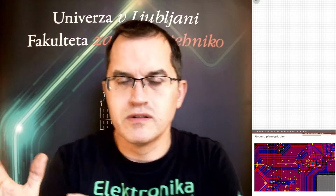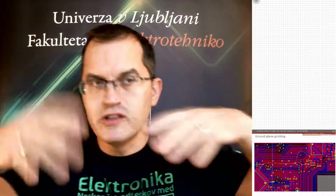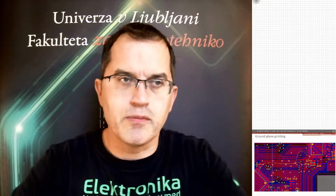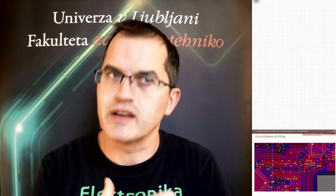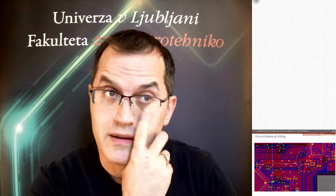You connect it to ground, try to move the lines around, move the tracks, move the wires, change from point to point until you find a big, nice, continuous mesh of top and bottom interchanging planes connecting the whole circuit as well as possible together. And that would minimize ground plane impedance and also provide a lot of ways for the current to return back to its source. However, you cannot do that well enough if you have high-speed circuitry.